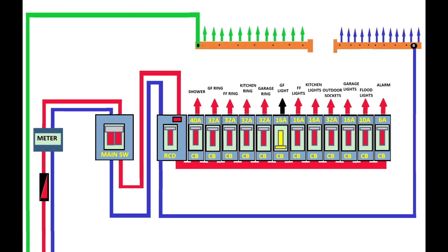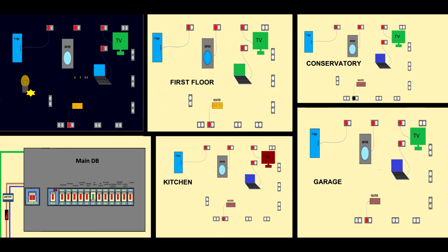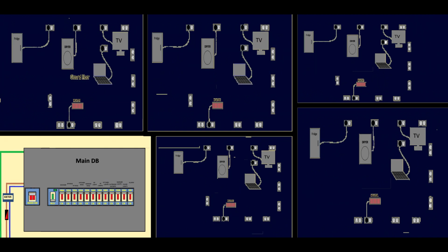Failing to secure a faulty circuit breaker can lead to accidental or intentional activation, which can result in the faulty circuit tripping the RCD, causing the loss of power to the entire home. So technically speaking, if you activate the circuit breaker of the faulty circuit, the RCD will trip and the entire home will be without power.